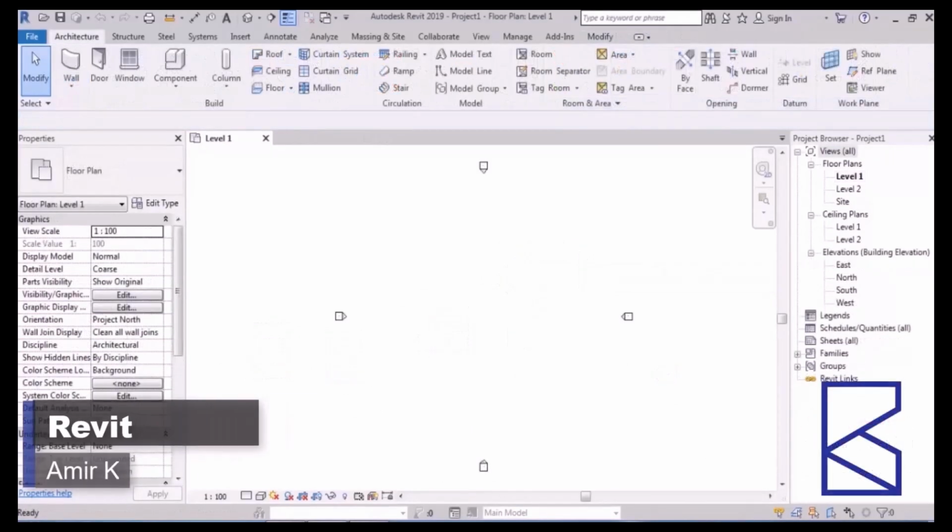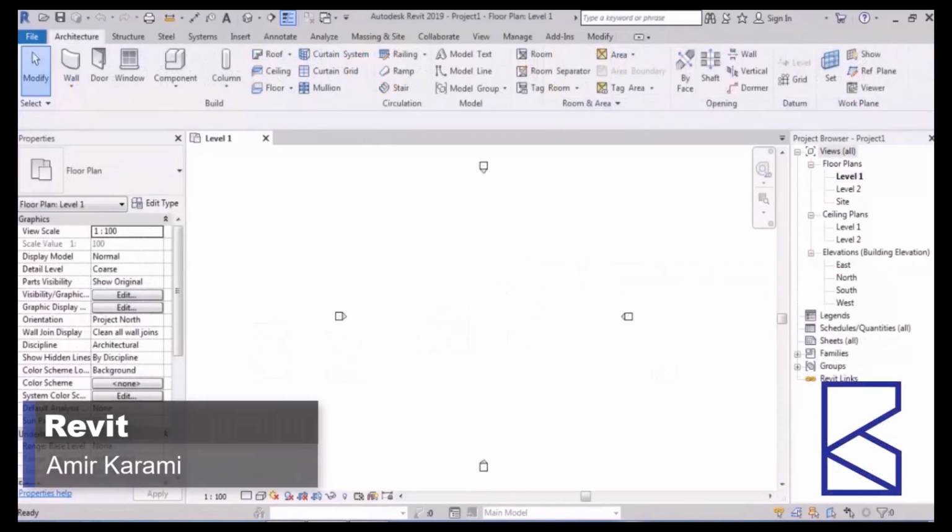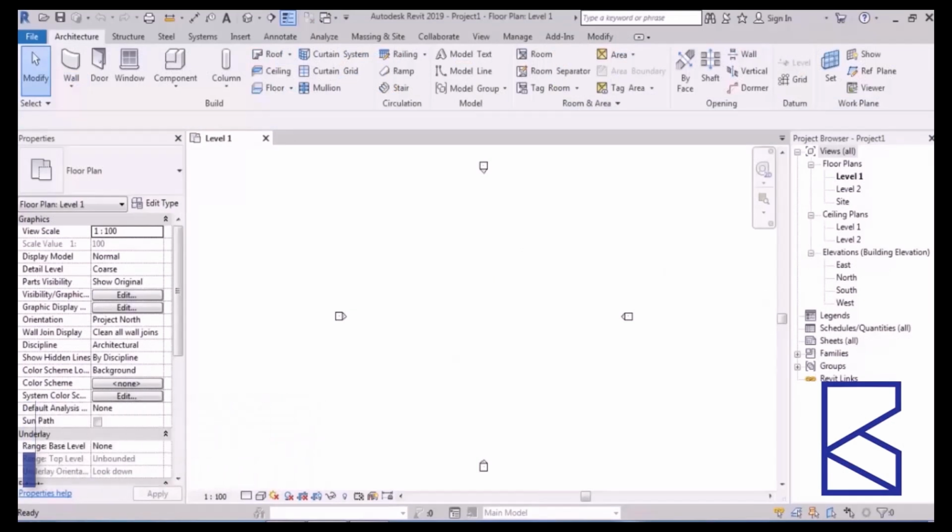Well, now let's go and analyze the different parts of the stairs. When you want to edit a stair, after drawing it, you need to be familiar with different parts of it. So, in the first level, we want to limit our edit only to dimensions. For example, increase and decrease the number of the risers, or I don't know, change the width and things like this.